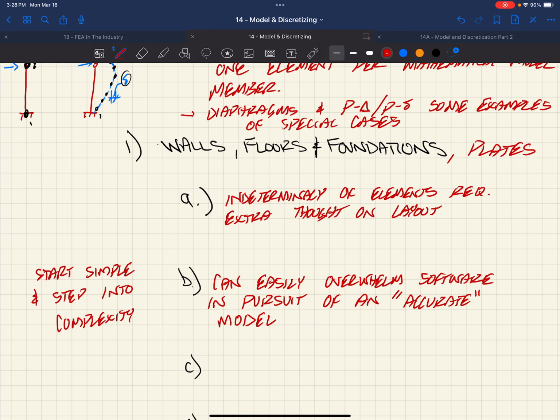And you might even try to start even simpler than that and load it up and make sure that boundary conditions are giving you the results and the behavior that you would expect, whether it's the displacement, or whether you'd get some torsion. If it was very simple, maybe a 1x1 box, with moment frames in one direction and brace frames in the other, you could probably calculate what the displacements are at certain levels based on mechanics, right? Axially loaded truss in one direction versus bending in the other with moment frames.